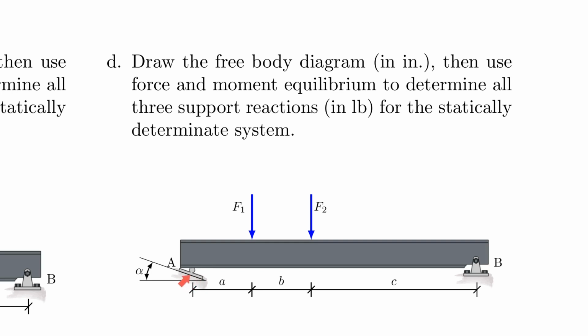So remember that this symbol here has a specific meaning, and I explained that throughout the lecture, so I don't have to repeat that right now. But there's definitely a force that is perpendicular to that surface. Sometimes there's also one that's parallel to the surface. But understand that in this case, the surface defines in which direction you have to find your support reaction. And so these 2 forces here actually act a little bit different if the support is angled. I mean, the forces act the same, but the support reaction reacts slightly different.